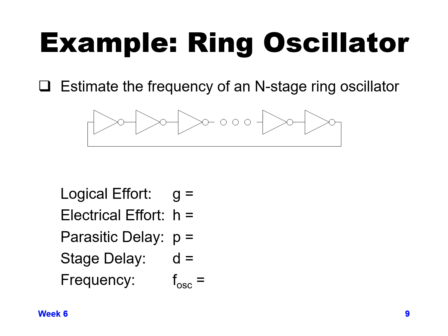If you construct it with an odd number of inverters, it will oscillate and cause a signal that will go from 0 to 1, and cause the next stage to go from 1 to 0, and then the next stage 0 to 1, and oscillate around the circuit. Since you have an odd number of inverting stages, it will continue oscillating around the circuit. Keep in mind, in order to oscillate, you have to go from 0 to 1, go around the circuit, and then it comes back around, goes from 1 to 0, and goes around the circuit. So you have to go around the circuit twice in order to get a full oscillation from 0 to 1, and then back from 1 to 0.